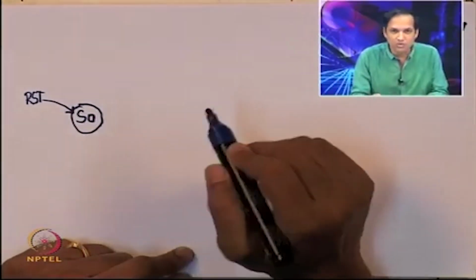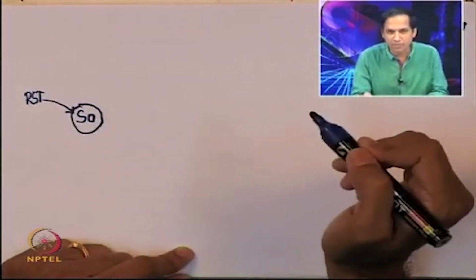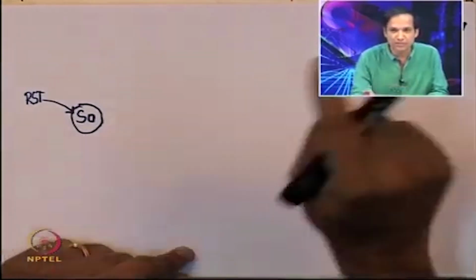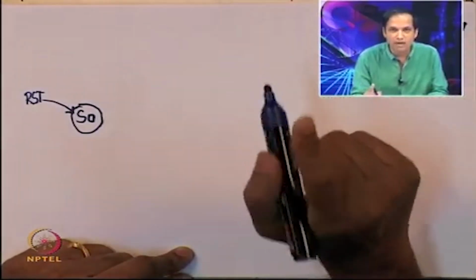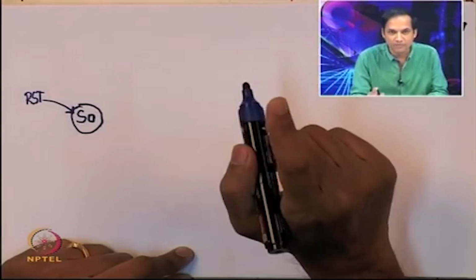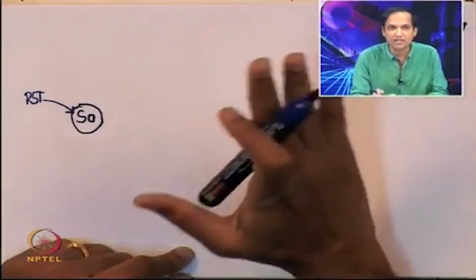If go is 1, then I can start processing, which means the state machine is supposed to tell the data path to take inputs and so on. But if go is not 1, which means the external world is not ready with the inputs, then the controller is supposed to wait for go to become 1.